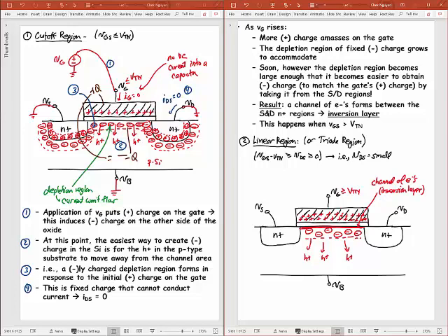is an inversion layer. And we call it an inversion layer because it has inverted the type of silicon that we have. Remember, this was P-type silicon. It was filled with mobile holes. But by putting this voltage here, we put enough voltage to invert this to something that's now full of mobile electrons. Okay, so that's why we call that an inversion layer there.